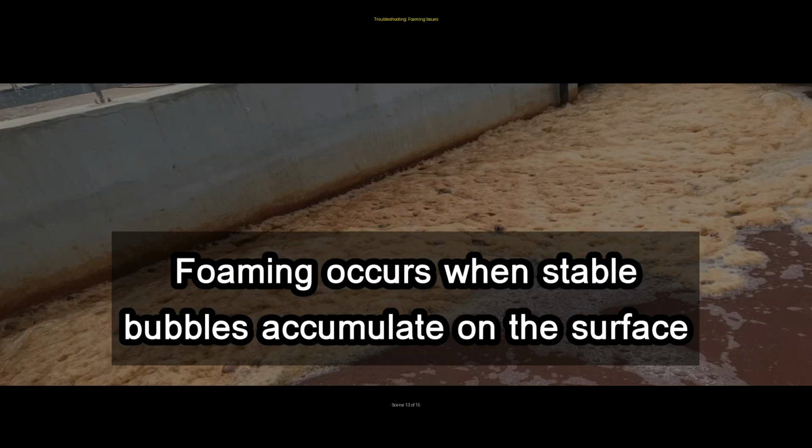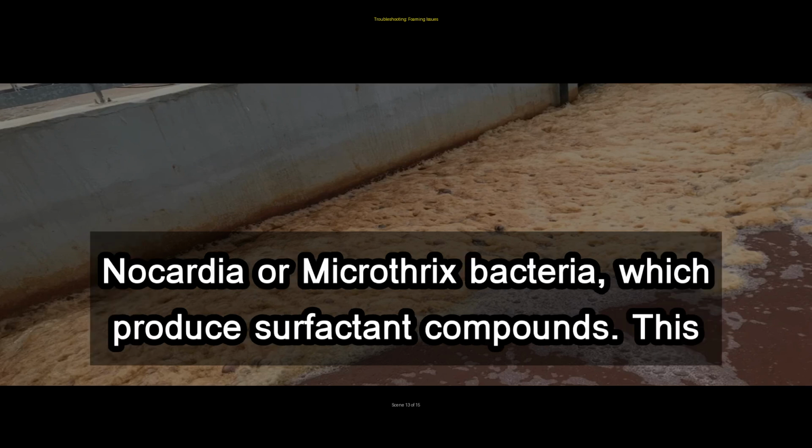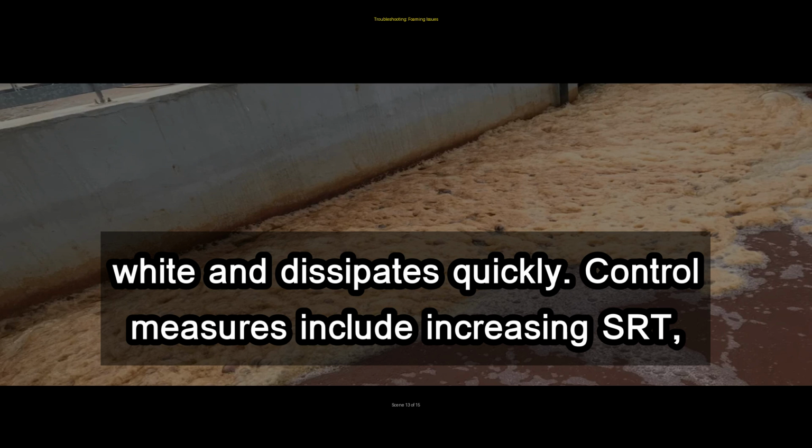Foaming occurs when stable bubbles accumulate on the surface of aeration tanks or clarifiers. Biological foam results from nocardia or microthrix bacteria, which produce surfactant compounds. This thick, brown foam can overflow tanks and create operational difficulties. Chemical foam from detergents or industrial discharges appears white and dissipates quickly.